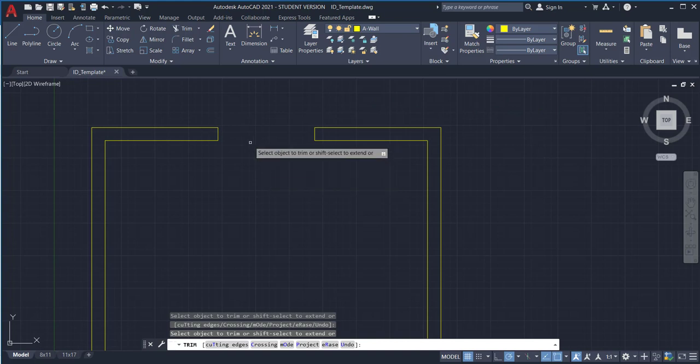I always say exit because it's always got a little red X on it, so exit, get it? Okay, so now I have a hole just like you would have if you had a wall and you needed to put a window into it. And it's important to have the wall layer on the sides of the window. That'll come in handy, and you'll understand why when we go to do things like reflected ceiling plans.